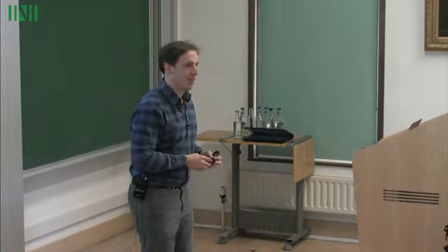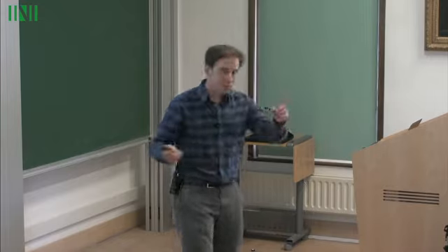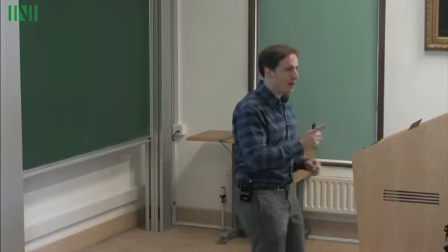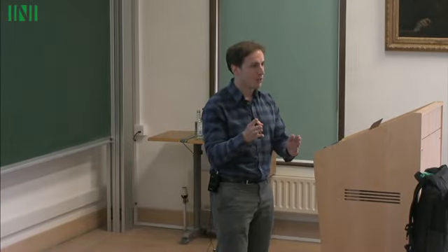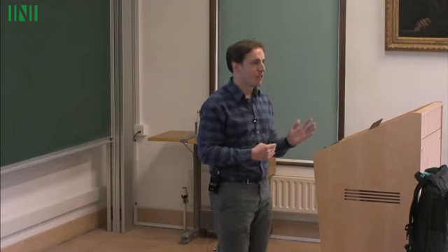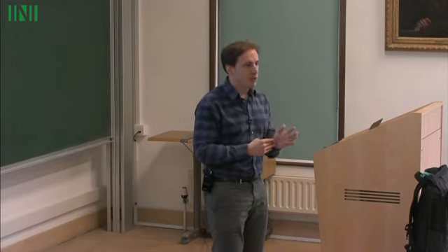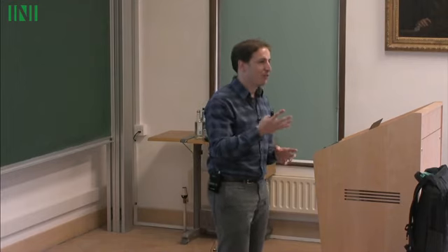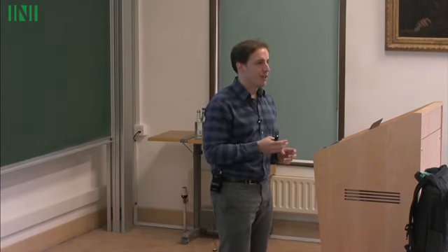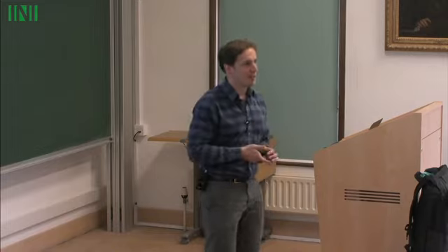And so I think Rocof is actually the reason why Ireland had some limits, and that was changed by redefining things. If you're really interested in a measure, it should be frequency deviation up to a certain point, and surely you need to quantify better what is the effect on the generators. But based only on Rocof, I'm not sure.